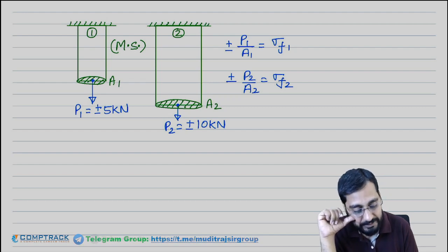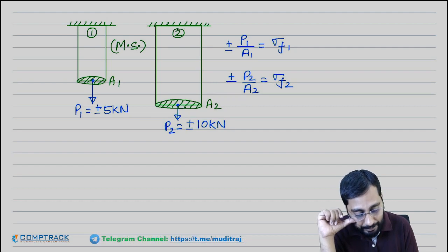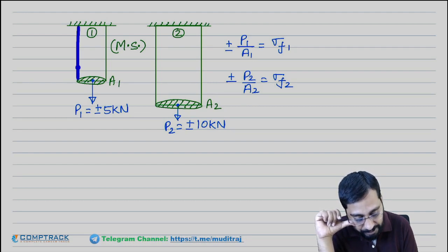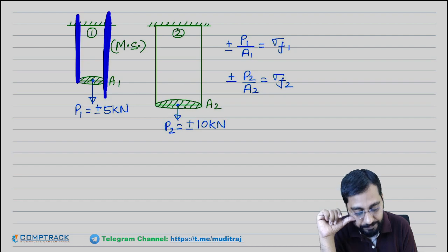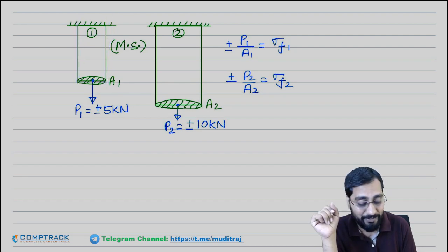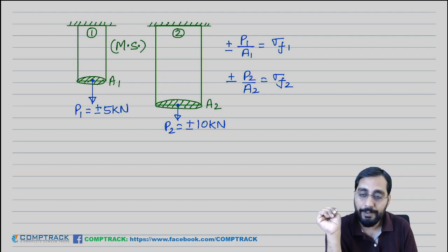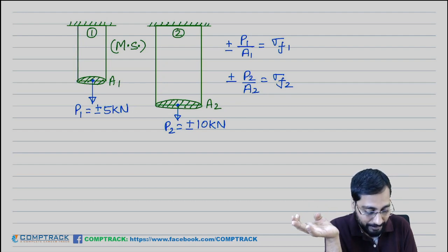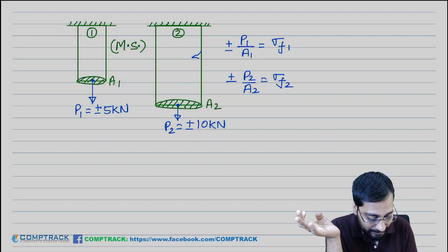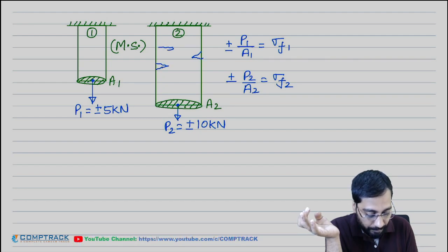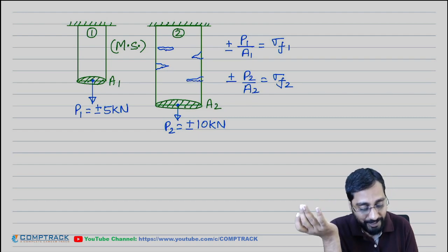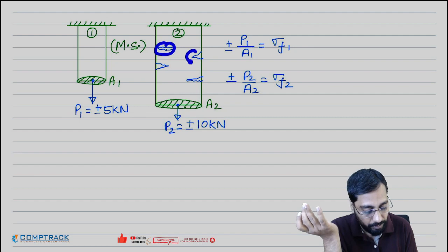Surface finish means if it is highly polished, then surface cracks etc. will be very less here. But in another material where there are surface cracks like this, surface cracks and internal cracks will raise the stress concentration zone. Yes or no? There will be stress concentration.